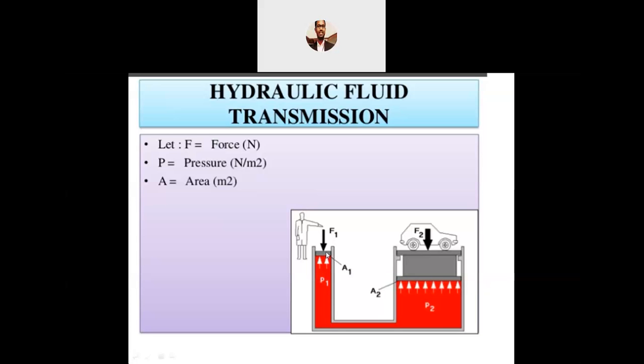It doesn't matter a lot. It is a mechanical element which we are keeping here to force the liquid, because however much you try, you cannot compress the liquid keeping it in your hands, right, my dear friends? So what we do is keep it in a container. Make sure that the container is completely covered with a piston or a plunger with a sealing arrangement. If you don't have a sealing, obviously whenever you compress, the liquid just comes out. So this I call a plunger or a piston.